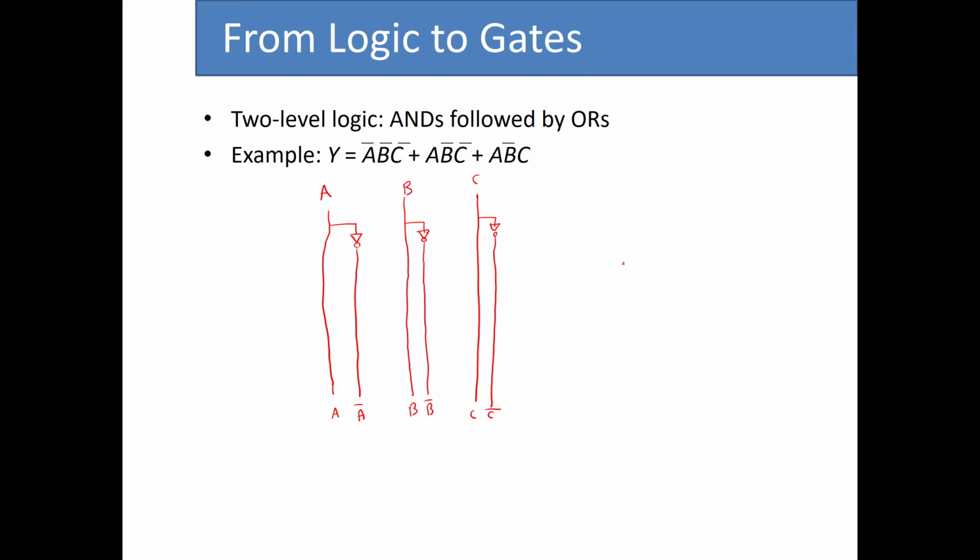Now what we have is three minterms that are created using 3-input AND gates. So I just put three 3-input AND gates all in parallel at the same level. And now I need to create the terms that each one of these produces. So what I do is that I connect the three inputs that I have here with the appropriate variable or its complement.